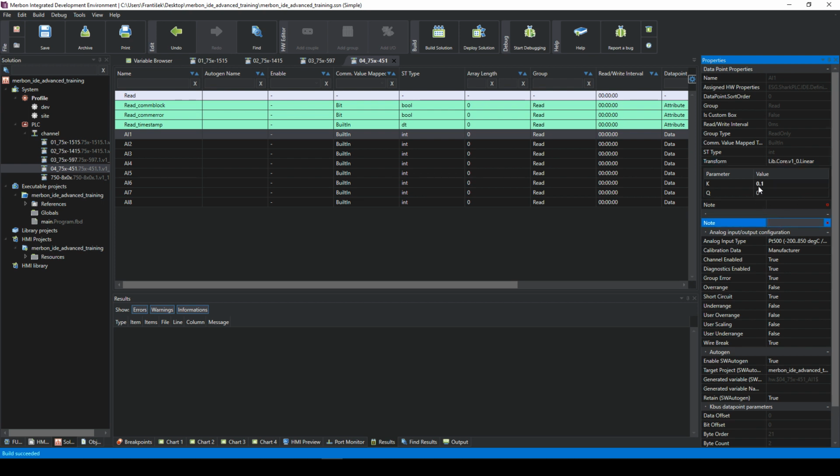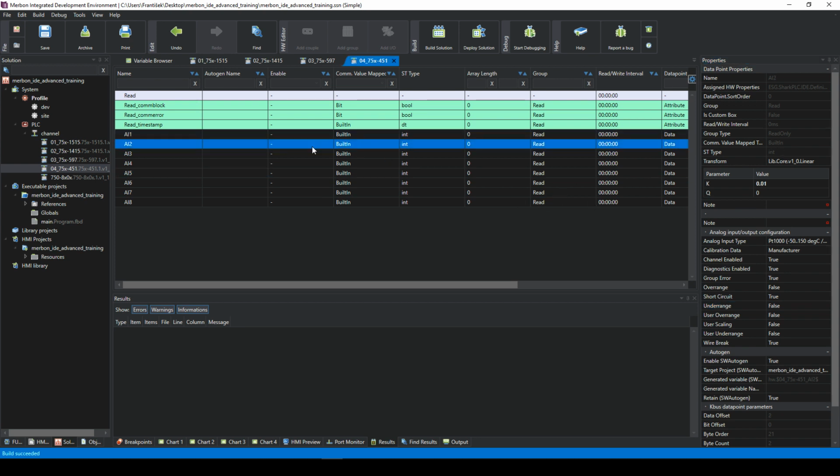The advantage of this is that there is no configuration of the modules as in our old IO systems. If you change it here in the program, it's automatically sent to the card itself just by deploying the project. So there is no need to configure the card by card or input by input. This is easier for you if you implement a Wago PLC or Wago series PLC.